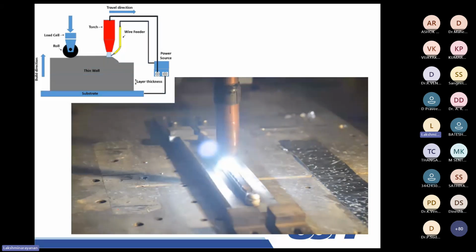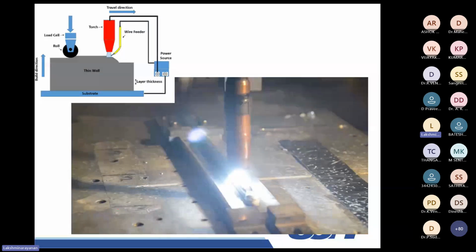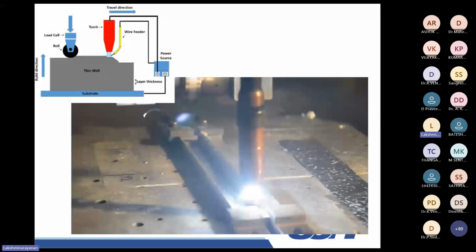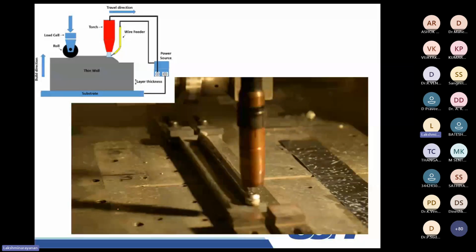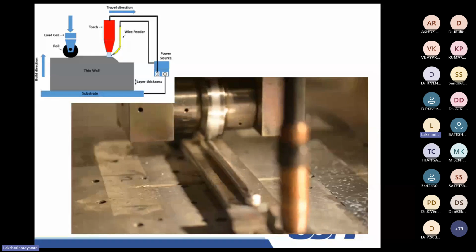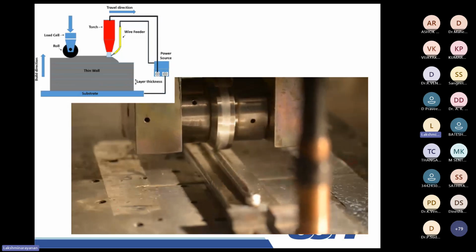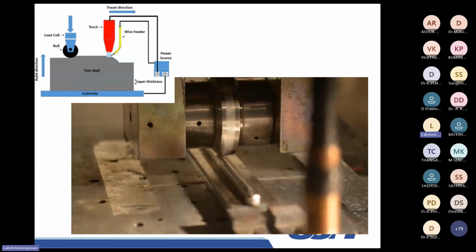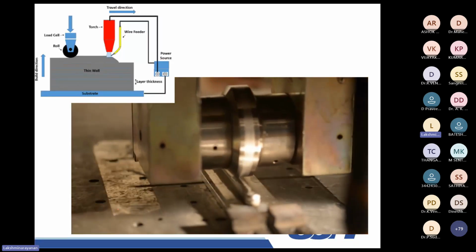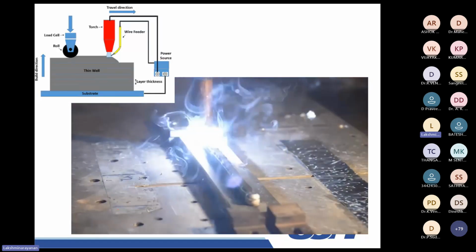Because whenever you melt and deposit, once it solidifies, tensile residual stresses will be induced. But tensile residual stress is not acceptable, not desirable, when you consider fatigue loading. This is one hybrid method. You see one deposition, then they use a roller to compress the deposited material. Here there are two things. One is to have compressive residual stress.